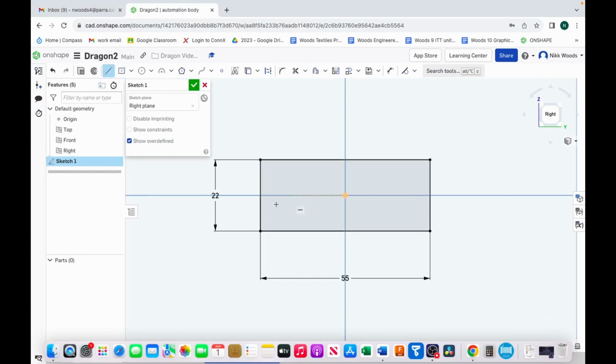So I'm going to use the pencil line to draw a construction line from the midpoint here. Click, click, type 5.5 for the radius, enter, escape. Line, this midpoint here down, click, 5.5, enter, escape, and we can draw our circles. Click, click, click, click. Our third circle was diameter 9 over here, so the radius is 4.5. Circle tool from that point there to that point there.